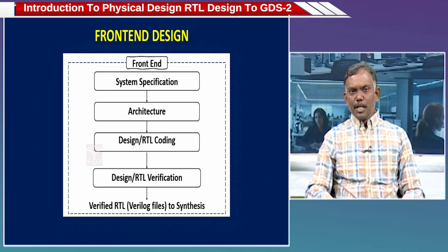Front-end design. Your front-end design starts with system specification, then architecture or design level, then RTL coding, design verification or RTL verification. These are the different steps in front-end design. Then finally, the output is Verilog files, RTL files to the synthesis.